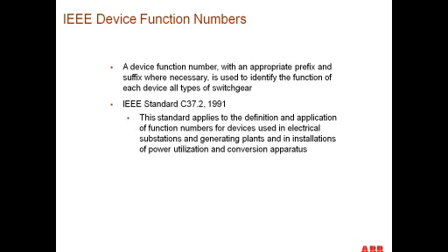The question is, are these protection schemes only applicable when using pilot? Yes, these schemes are all pilot. Pilot protection means I'm using a communication scheme to talk between one end of the line and the other end of the line. And yes, all these permissive overreaching and permissive underreaching schemes that we talked about are all schemes that are used with pilot protection, so that we get 100% clearing for the whole line for any internal fault. That's right.